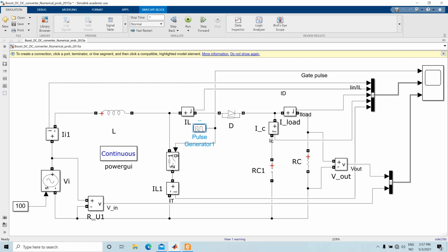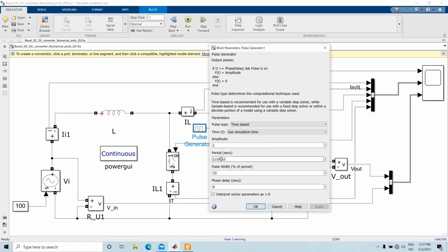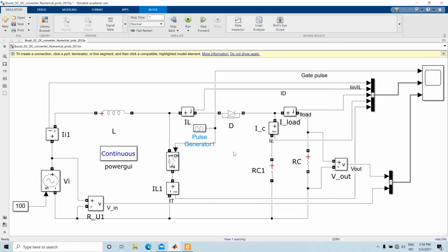You can also play with the switching frequency, but in that case the other parameters will also change. This is an option, though it is not often done by changing the switching frequency, but it can be done. The easier option is to change the value of C for a certain ripple voltage.